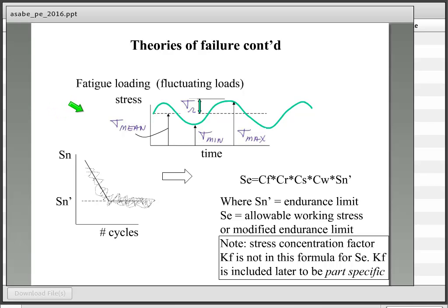If we were dealing with a rotating shaft, for example, that had a sprocket or a V-belt sheave on it, where as it rotates, the shaft is seeing a reciprocating load, any fiber on the surface of the shaft would be undergoing compression and tension during each rotation due to the bending stress in the shaft that would result from the load from the chain or the belt or the gear.